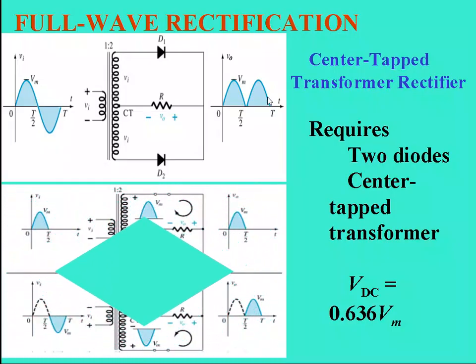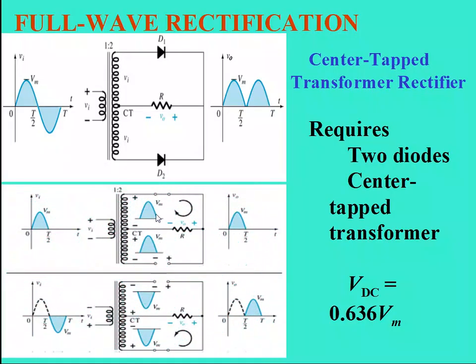And here if you see, when the positive half cycle is coming, this will conduct, this will not conduct, and the current will flow in this direction. So the circuit is completed. Similarly, when we come to the negative half cycle, the current will flow in the opposite direction, and ultimately the circuit is complete. So we will get the negative half cycle on the up. The direction will not change, so here the direction will come up. So that is the utility of the full-wave rectification.